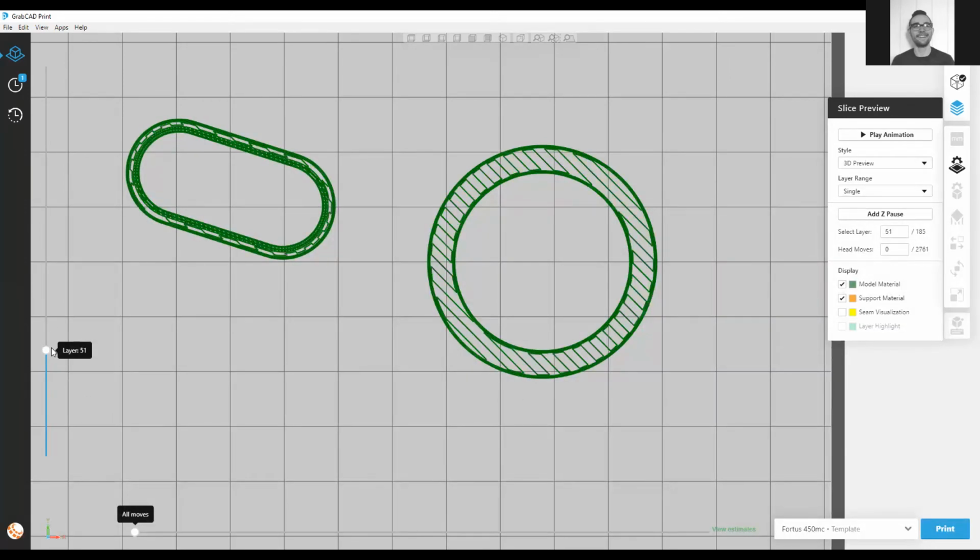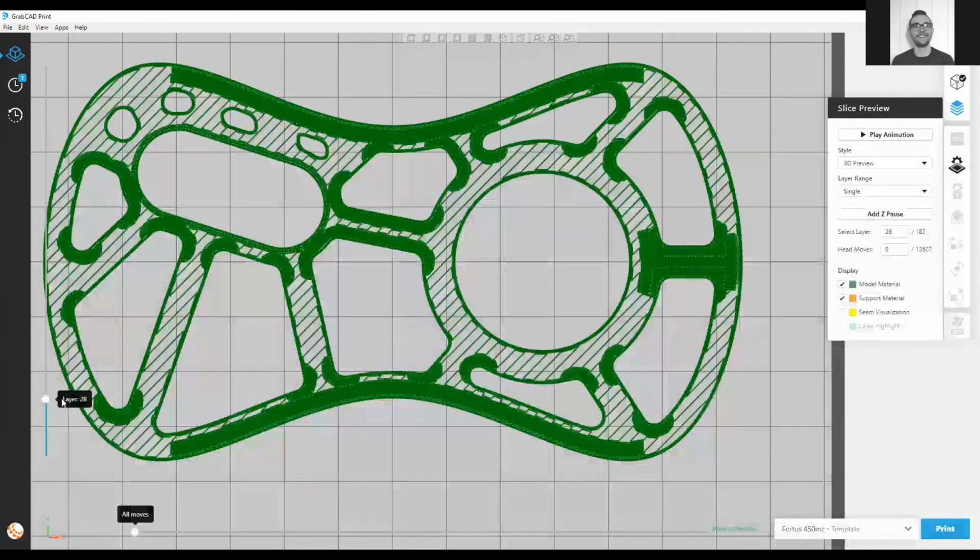And we scroll down even further, again, we can see where that reinforcement has stopped. And now we're in the part and we can see how complex we've gone. So you can see the two stiffening beams on the top and the bottom, as well as the I-beam here. And then you can also see the 200 thou reinforcement that we've done on all of these fillets. So by providing a solid infill here on all of these fillets, it adds strength to the part, helps us prevent flex around these points, and ultimately will lead to a stronger part. Now we'll pop back into the presentation and continue on from there.